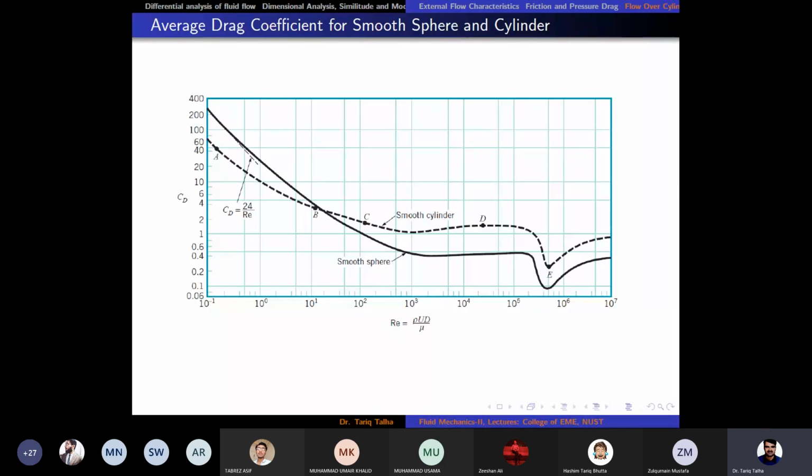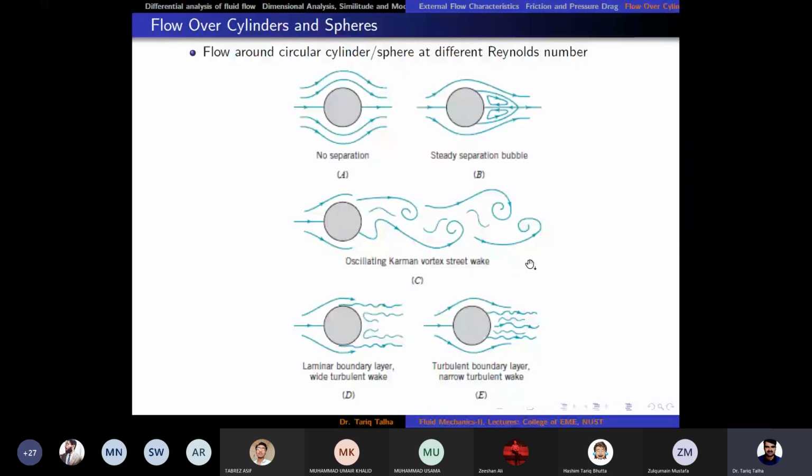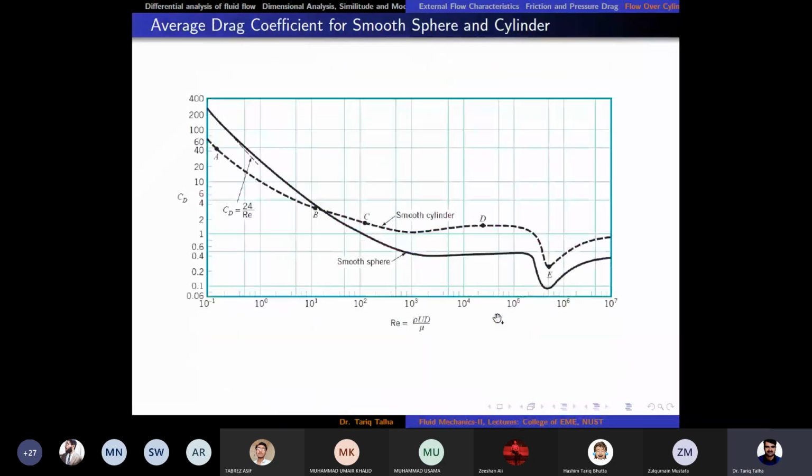So that is the point where the flow becomes laminar to turbulent, right? As I have explained, the wake region becomes smaller because the flow separation occurs at theta equal to 140 degrees. So that's why we want the golf ball to travel in this region, so that it has a very low CD value.